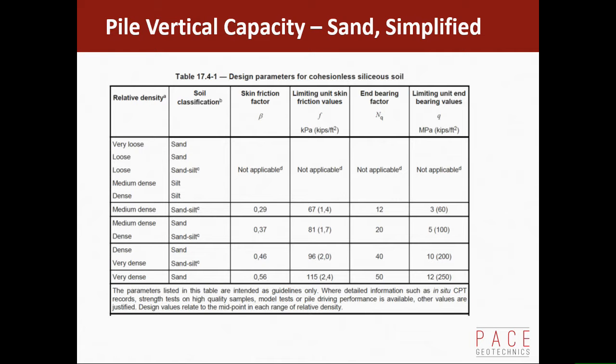Okay, that is quite a useful table, and you can certainly do a first pass pile design on that, and that's useful if you're just costing up a job or getting a feel for how deep a borehole needs to be. But as I say, I would recommend that that's just a first pass, and detailed design uses one of the commentary methods in API.